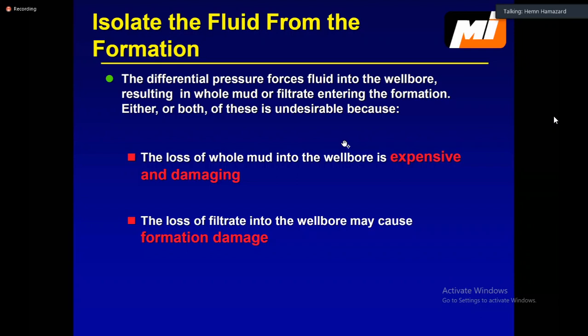So that's why it's also important to have a proper mud weight. If it's more than the formation strength, then besides the fluid losses, you also have a problem with differential sticking.